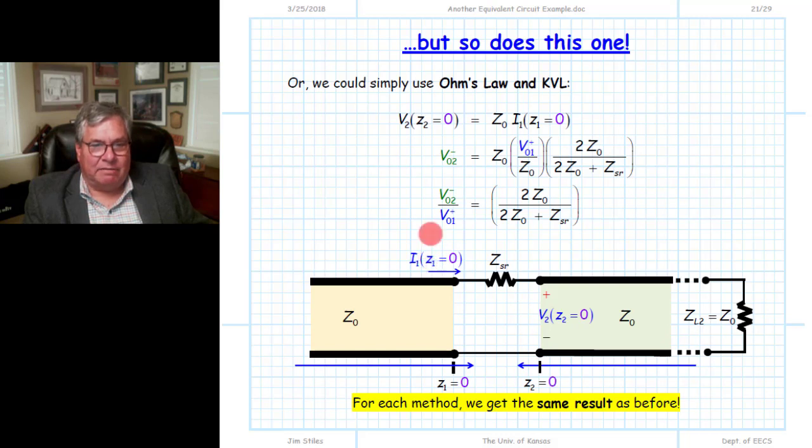And clearly then if we have this I1 times that goes through that 50 ohm resistor, and the resulting voltage across that input resistance of 50 ohms will be by KVL equal to V2. So we put the pieces together here, and this is the result. V2 is equal to I1 times Z0, Z0 being again the value of the input impedance for this structure, and by KVL that voltage must be equal to the total voltage V2.